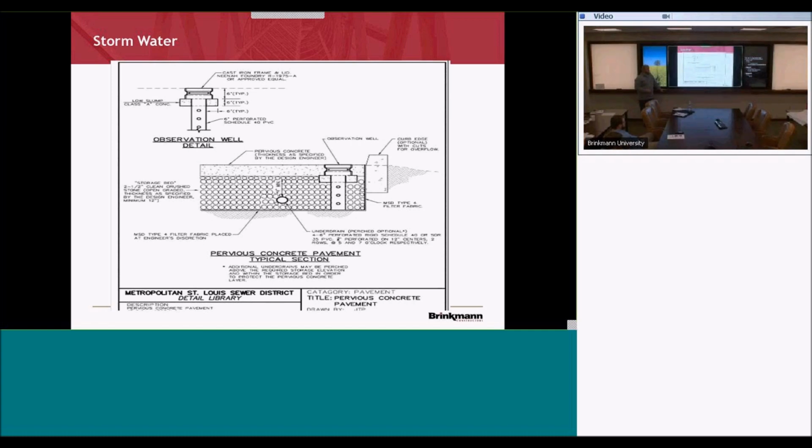Yeah. Depends on which project you have and the timing, but that diagram doesn't always do it justice. I mean, some of those are 4 or 5 feet deep. So if you buy the sewer guy just to put the pipe and go away and have your paver come back and add 4 or 5 feet, where's your curb guy go? Does he go before, after? How's he going to set off his pins and things like that? So it gets to be an issue to figure out and have a lot of meetings to make sense. But in my opinion, the majority of that rock's typically by your sewer guy.